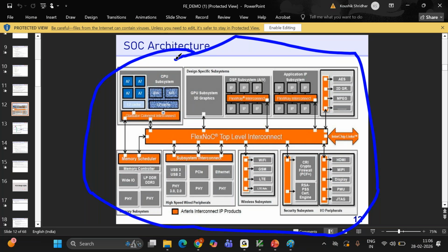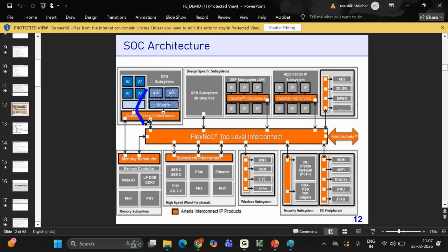Understood? SoC verification is done using a C-level language, because the ARM processor understands assembly-level code. So you will write C code. C to assembly conversion is taken care of by the ARM linkers and compilers. So the ARM generates transactions using the AXI bus, for example, to the USB controller.